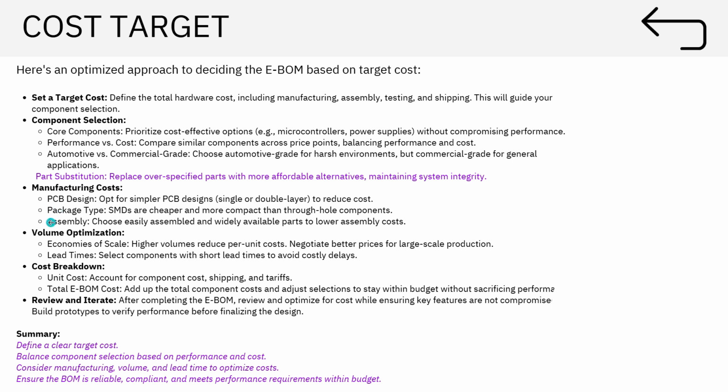And when it comes to layout, when you design the PCB, you might be placing all the components at the top. During assembly, the pick and place, one side is where all your major components are. On the bottom side there might be some minimal operations in terms of component placement and soldering. So that might affect the cost.